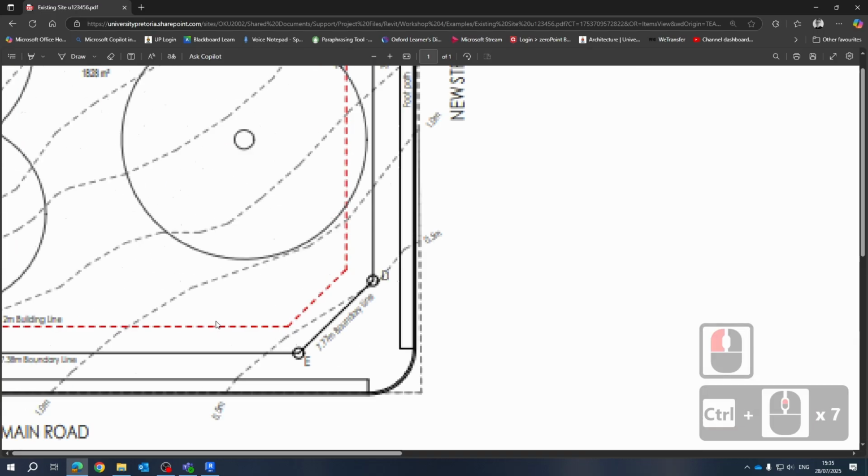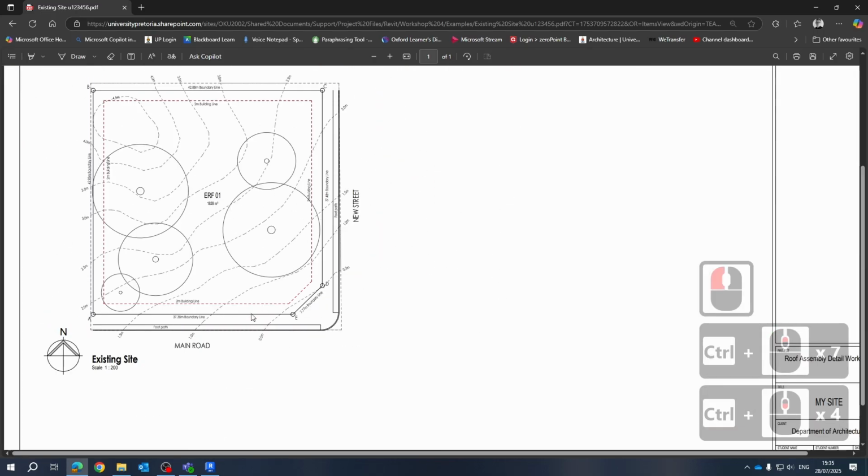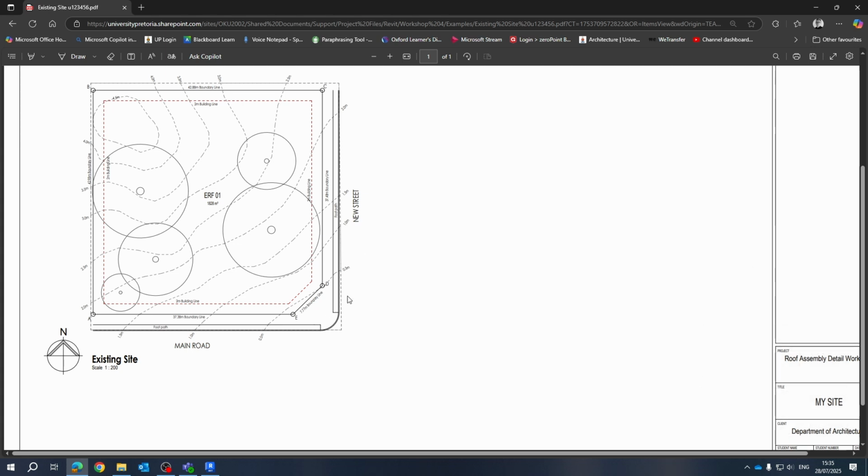So it's an existing site with major and minor contours at 500 intervals. Remember we represent that information in meters because it comes from a surveyor. So there's certain things that we'll always represent in meters, like site boundaries and contour lines, because we're communicating primarily with the civil and structural engineers and surveyors. Okay, so it'll be civil engineering, surveyor, and structural engineer that will need this information in meters primarily. It will depend, but as a rule of thumb, this is always in meters.